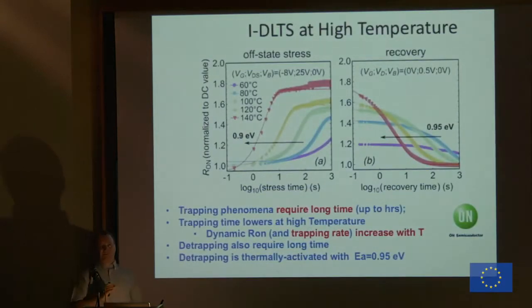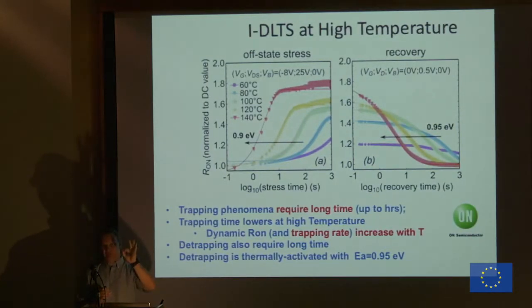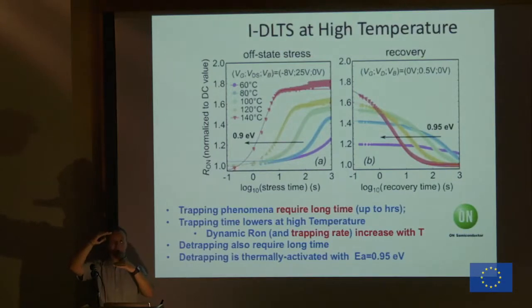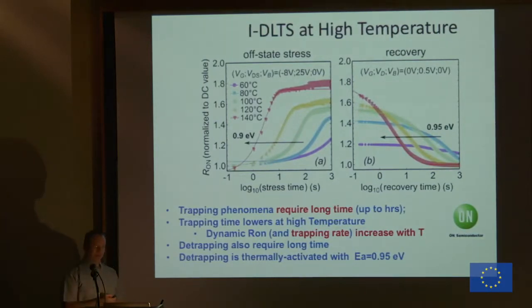In the simple physics of trapping, you make a big assumption: the trapping time for electrons when one reaches the vicinity of a trap is 0. Trapping time is 0. And when the electron is within the trap, to escape, it takes time that is proportional to the activation energy, which is the energy between the electron level and the top of the trap, okay? So it's just the energy that electrons need to escape from the trap. But again, the assumption is 0 trapping time.